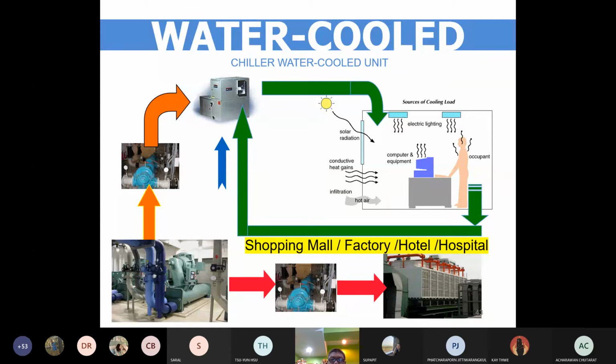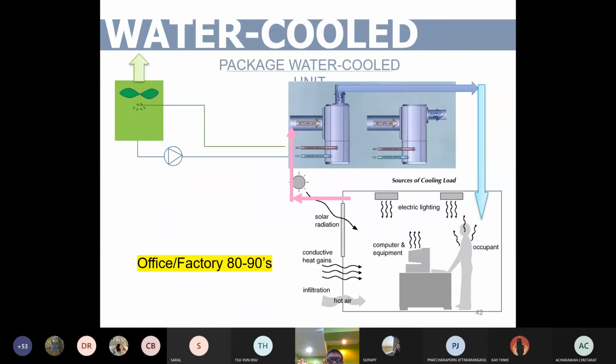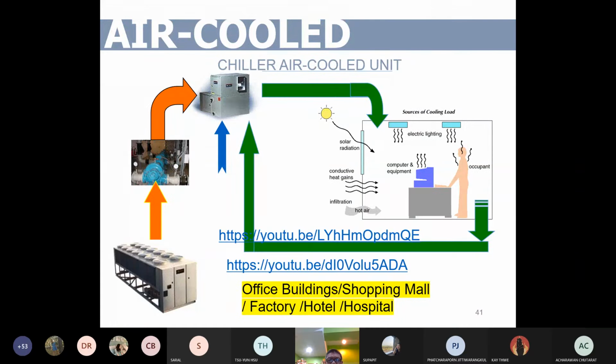But the majority of hotels in Thailand have 88 rooms, so this may not be a good choice. So the air cooled chiller is very easy to install and maintain, and cheaper than water cooled. But comparing air cooled and VRF at the moment, the VRF price has come down. In some cases, they are even cheaper than air cooled chillers, and more efficient.